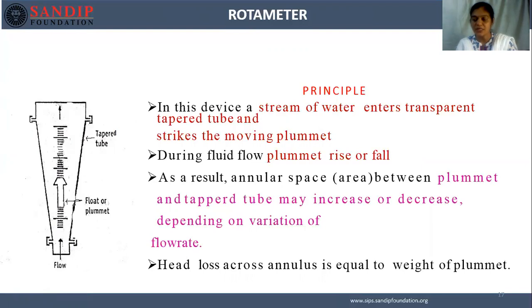This rotameter is available with electric and electronic transmitters for recording. Floats of different densities are available, so that a 200-fold range of flow can be measured accurately. And what is the float actually made of? It is made of either lead, aluminum, glass, as well as plastic.